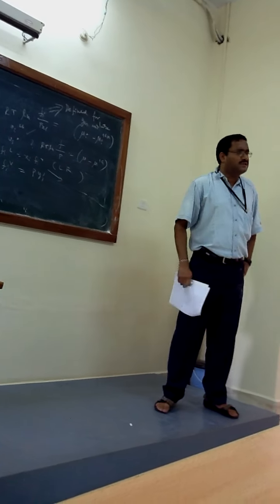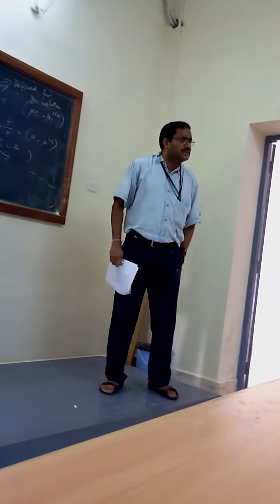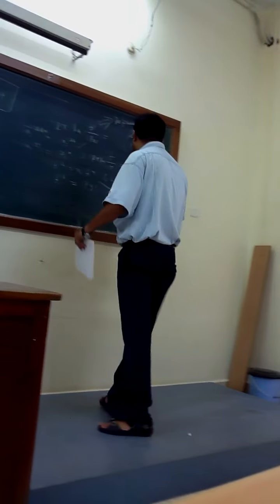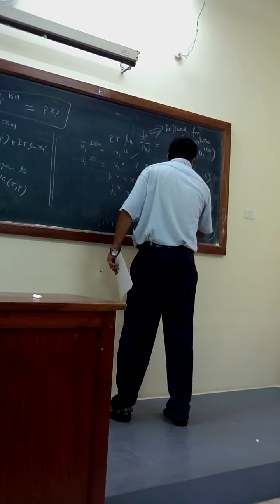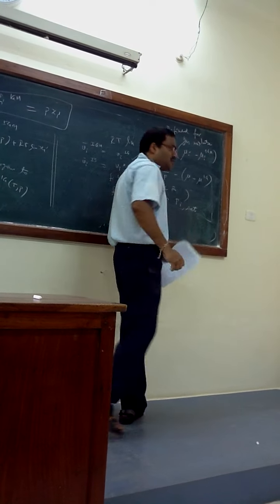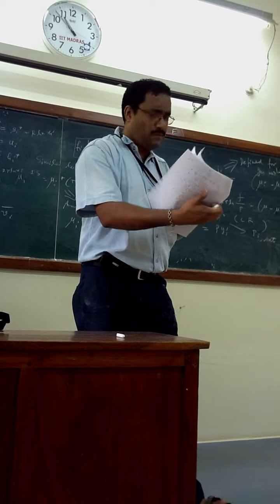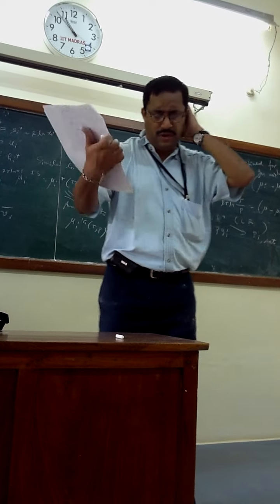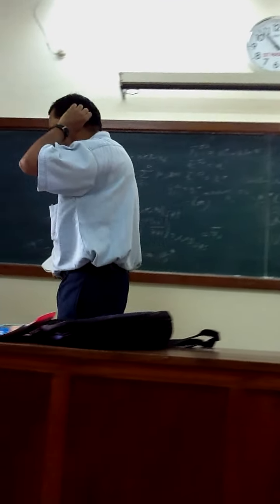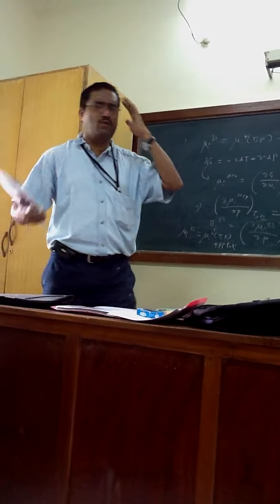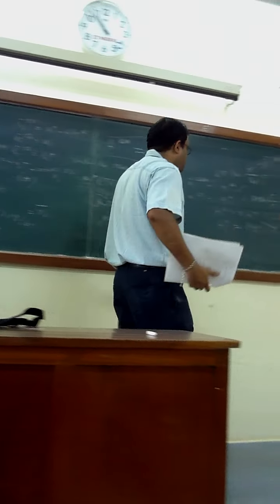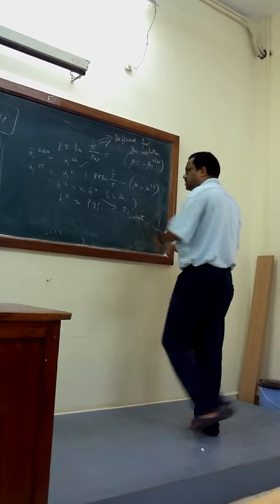Do you remember that saturation pressure? So pure substance fugacity is nothing but saturation pressure, neglecting Poynting correction. We have done earlier that f by P that we have calculated with the Poynting corrections, and if you look at that pure substance fugacity, it is nothing but the P_i saturation pressure.